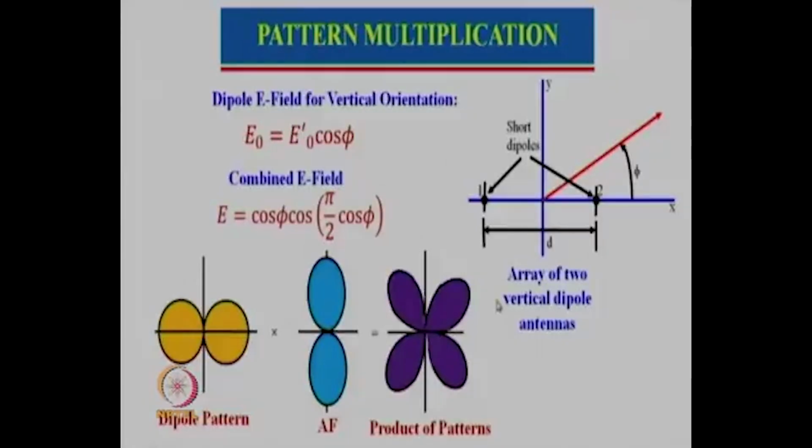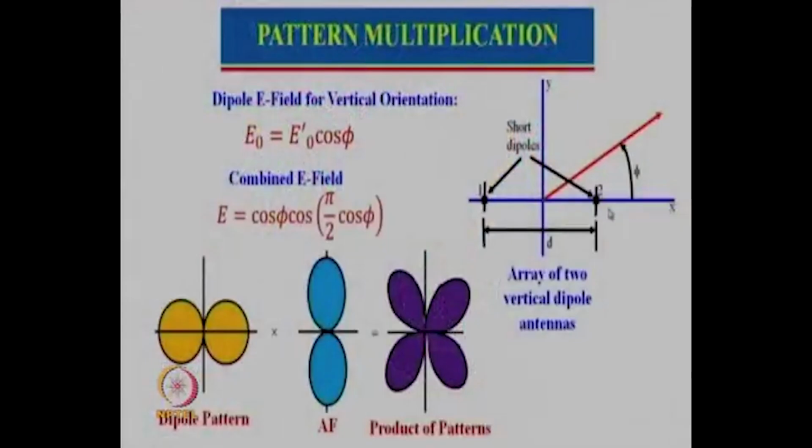But suppose you just thought of this as a dipole antenna and you are going to place it, orientation is very, very important. If you put it horizontal, then the beam maximum will be this, but if you made a mistake of putting it vertical, and you are trying to make the measurement in the broadside direction, you will actually get a 0 value, and that actually creates butterflies in your stomach. That is what the pattern is about. So please ensure how you place the antenna, what the orientation of the antenna is, and how you feed the antenna. Of course, this vertical arrangement will be the perfect case if you are designing an end fire array.